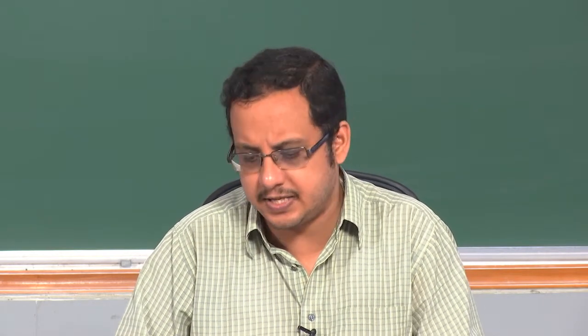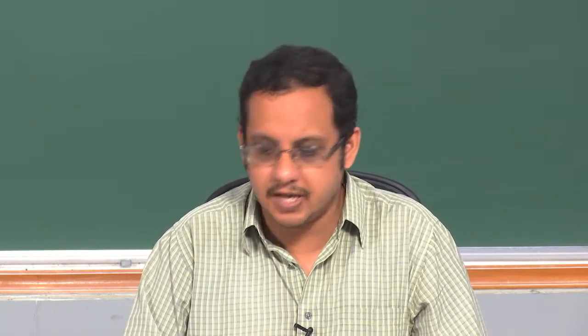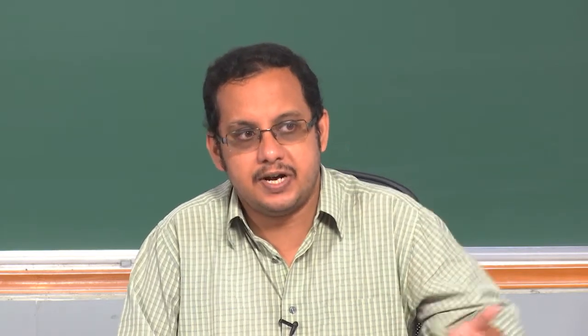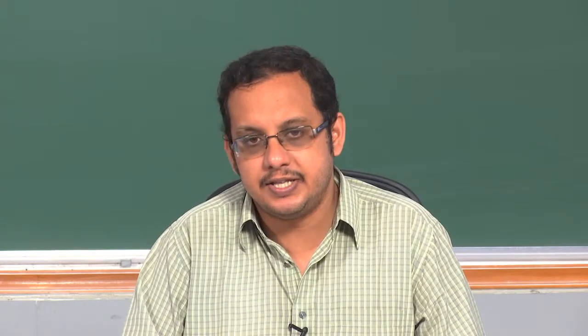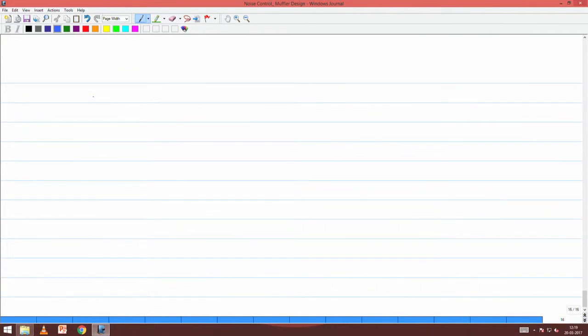But then when I say high expansion is preferred, so you give as high as possible, 100, 200, what stops you from giving a very high cross sectional area? Space. Definitely you cannot give a very high area for the expansion chamber because the ground clearance in the vehicle will not permit so. But let us say you are talking about a tractor where the muffler is actually on the outside, right. Muffler does not go on the ground, it goes upwards. So, there is no space constraint. So, what prevents you from putting a very large expansion chamber in a tractor? Back pressure, right.